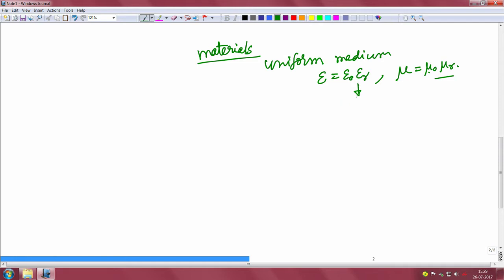As we know, the refractive index is defined as the velocity of light in free space divided by the velocity of light in the medium. So, by considering the frequency and wavelength of operation, we can express n in terms of epsilon r: epsilon r is n square. Of course, it depends on the operating frequency, but at a given frequency we can express the relative dielectric constant in terms of the refractive index profile.